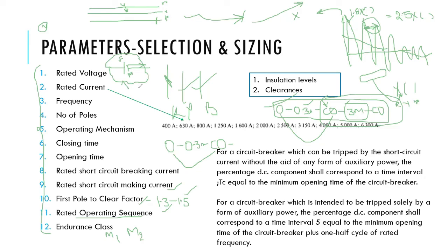Now if you close the breaker again and a fault occurs and it opens, the breaker will blast because it is not able to quench that arc, as there is no sufficient dielectric strength. So we give some time to that breaker, which is 3 minutes as per IEC standards. After 3 minutes, you can close the breaker, and again the operation repeats. Clear?